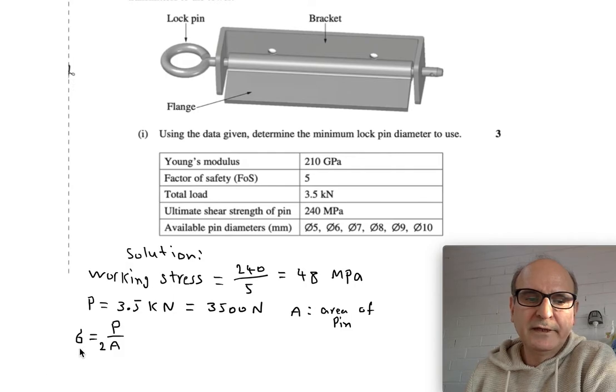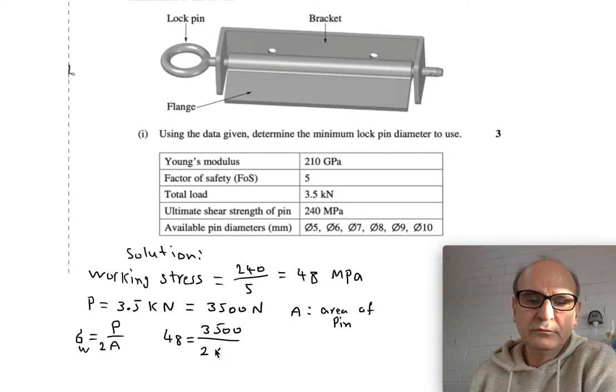So that's the working stress, which we found to be 48. So sub in 48 is equal to load, which is 3,500 divided by 2 times A.